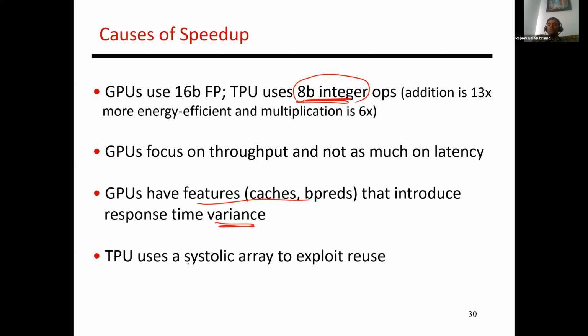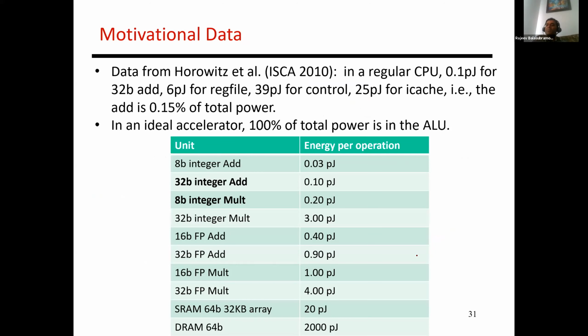Okay, and then like I just showed you, what I just described is known as a systolic array, right? Where you have flow of operands from left to right, top to bottom. When two operands collide at a certain cell, they do a certain operation there. And this maximizes reuse, which says that if you've taken the trouble of getting a weight or an input pixel from some large buffer, let's try to maximize the number of computations that I can do with that operand.